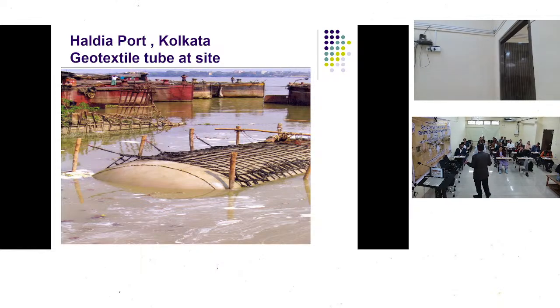So how do we use it and where do we use it? We can use it for coastal protection. So wherever there are coastal erosions, we can use geotubes. We can make embankments of geotubes. And how are these geotubes installed? You lay these tubes and then you pump sand slurry into them. You are pumping sand slurry, so what is happening? The water is moving out and the sand gets contained into the geotube.